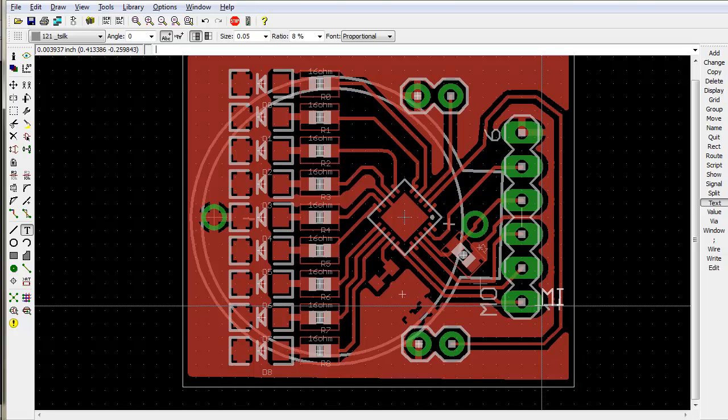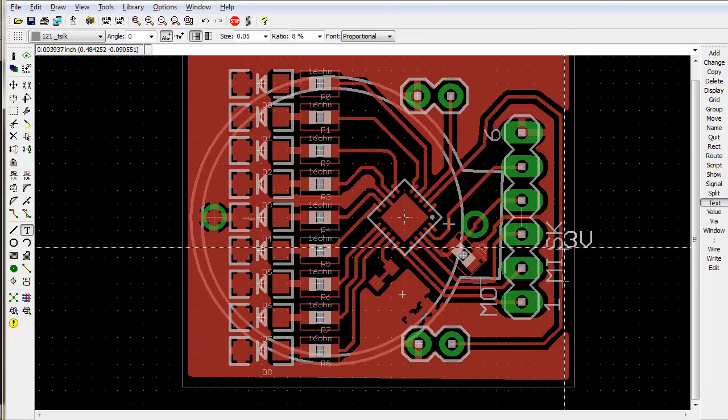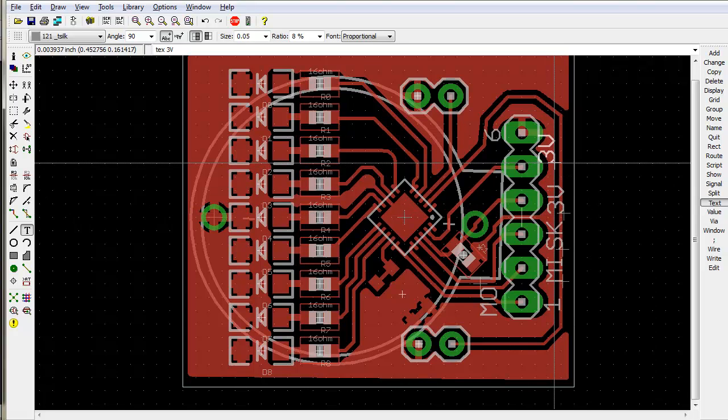And these are the non-standard pinouts that I used. And you can see I'm using the text command, obviously. I don't think I actually explained that, but I'm pretty sure it's fairly obvious. Okay, look at that. So Eagle lets you use the bare minimum of letters to differentiate the commands, and with text, obviously, it's TX or T. That's the reset. So we're adding labels on the silkscreen. And finally ground, which we're going to use G.